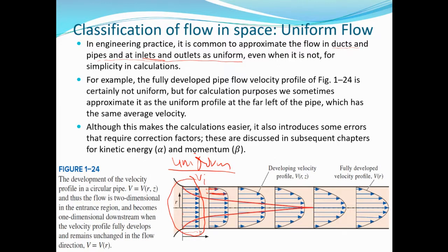Now talking about acceleration again, the velocity at this point is different. When you look at the center line streamline, which is this one, is the velocity changing? At this point, the velocity here is less than the velocity here. It increases again. You can see the velocity increasing.